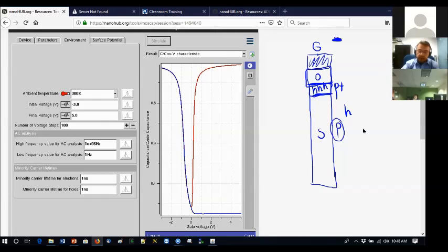And you know how the capacitance is found. It's epsilon times area over D. If you do not remember the simple formula, D is the thickness. Area is, if you think about it in 3D, the area here. And epsilon is the dielectric permittivity. In this case, it's silicon dioxide, so that's the relative dielectric permittivity of silicon dioxide times the permittivity of free space. Anyway, those are details, but this is the capacitance.